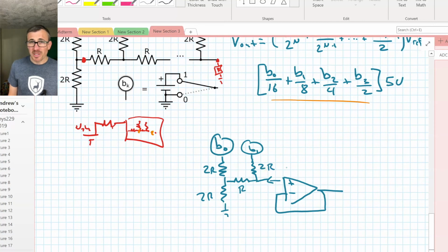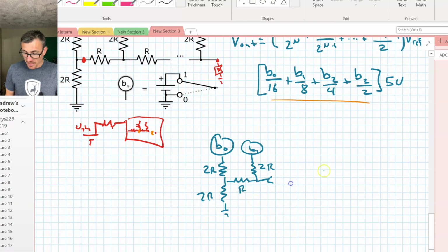You can do tricks with the inverting one, like set a virtual ground halfway through the maximum reference voltage, but I think this is most straightforward. So we're just going to put an infinite resistor, say, a buffer op-amp, an ideal load at the end of this thing. All that is to say is that we don't really need to worry about what happens here in this analysis, because it's going to be like an op-amp that draws no current.